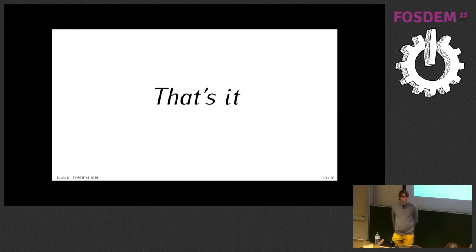How do you handle parts that are just on the PCB, like a spark gap or a test point that is not orderable, but is just artwork? So the question was how parts just on the PCB are handled right now. Right now they aren't. Test points also, in my opinion, have to appear in schematics so you know where they should be logically, and things like spark gaps should in my opinion also appear in schematics. So these should also be included in the pool. But still, there's an option missing to make them not appear in the BOM output. The main reason for this is that no one has asked for it yet.